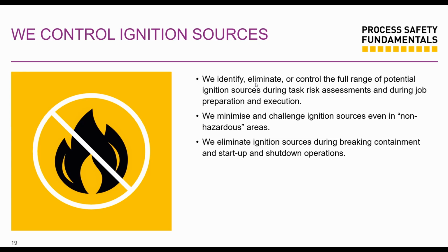So we identify, eliminate, or control the full range of potential ignition sources during task risk assessments and during job preparation and execution. This is very, very key. We are using the right tools. We are using intrinsically safe equipment. Minimize and challenge ignition sources even in non-hazardous areas, because hey, we could have gas clouds that travel and cause ignitions, and eliminate ignition sources when we're breaking containment.